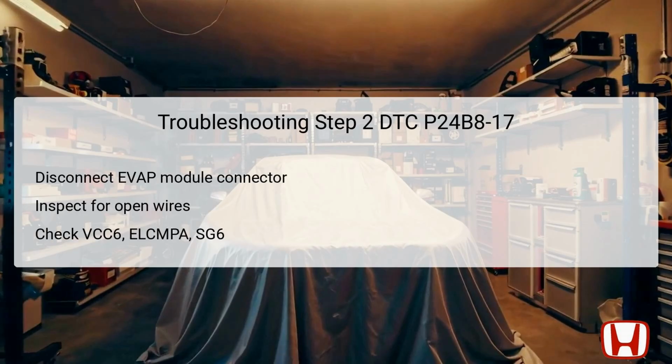In the second troubleshooting step, you will disconnect the evap leak check module connector and the PCM connector. After disconnecting, perform an inspection for open wires in the related circuits, particularly focusing on VCC6, ELCMPA, and SG6. It's essential to check for continuity, where normal conditions should indicate less than 1 ohm of resistance. This ensures that there are no breaks or faults within the wiring that could lead to erroneous readings.